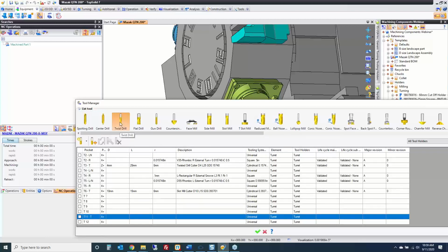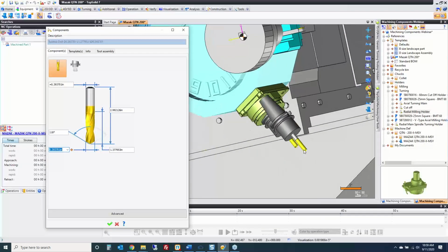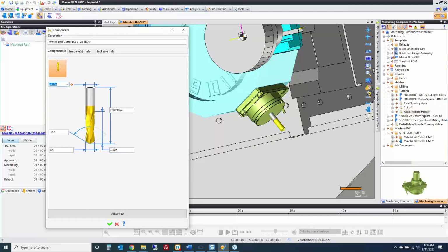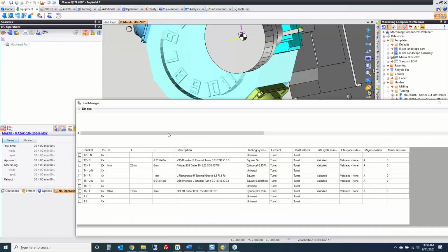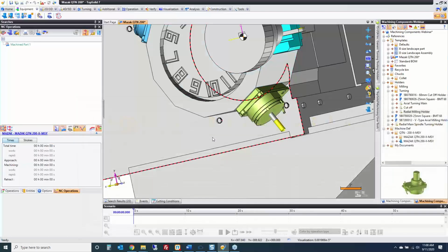Who knows? Okay, so a double click. Notice that this is showing a holder. If the type of tooling system you're putting in accepts quick change tools like this, you're all set. If it just is a collet-based solution and you just need the stick tool, make sure you go to templates and choose just the stick tool. Then you can set it to whatever you want it to be. I'm going to say it's a 1/2 inch, 1 1/4 of flute, why not? 3.5 inches long. And if we go here, you'll notice that you have, of course, the ability to play with its gauge distance. Perfect. And now we have another new tool and a new holder combination. And you can reuse this as much as you want.